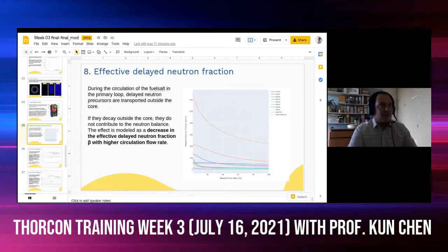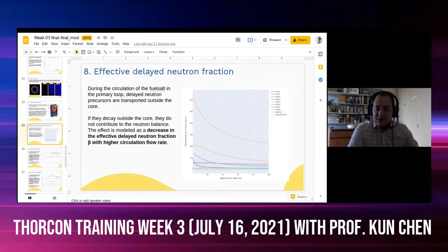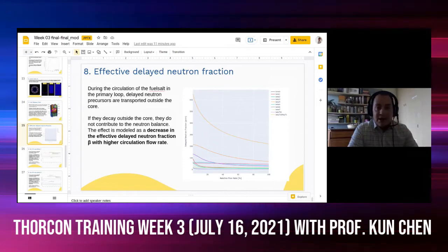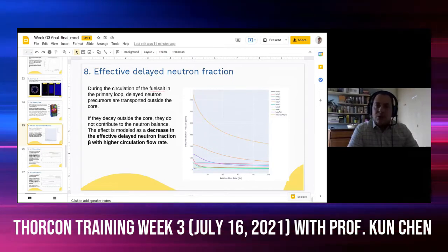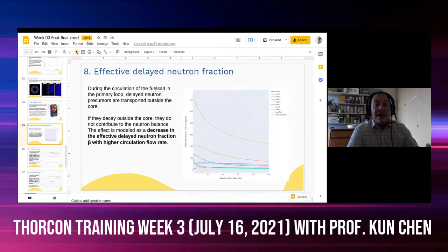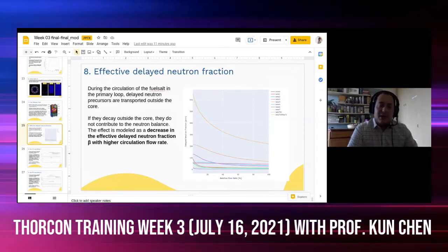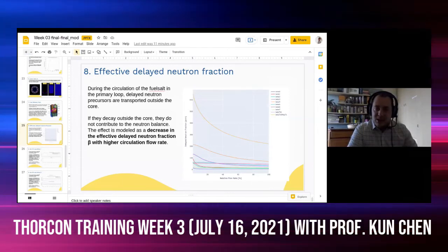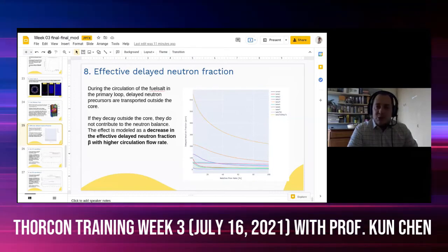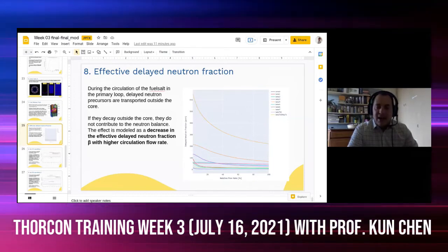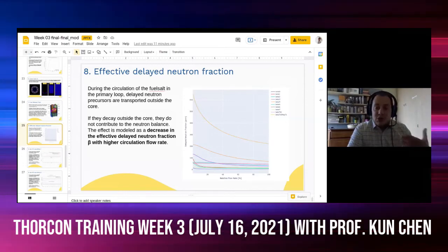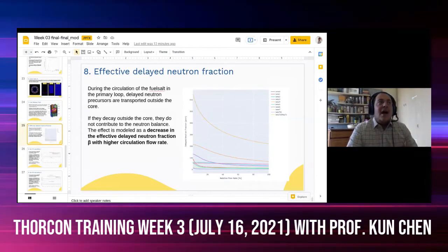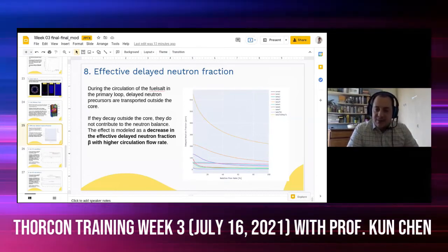So since it is possible, in principle, to operate the reactor with a variable speed pump and a variable circulation flow rate, even if this is not in the present control design of the ThorCon system, in that case, we will have to take into account that reactivity, beyond the reactivity feedbacks due to temperature, is changed and introduced due to the different flow rates. And effectively, if we stop the circulation, either voluntarily or by accident, around 300 ppm of reactivity, or slightly above